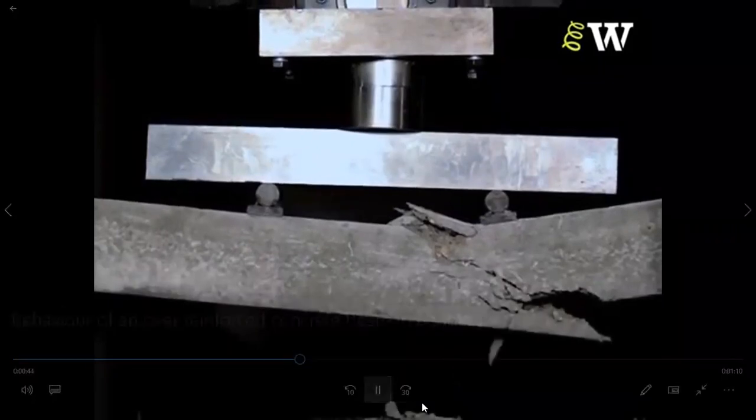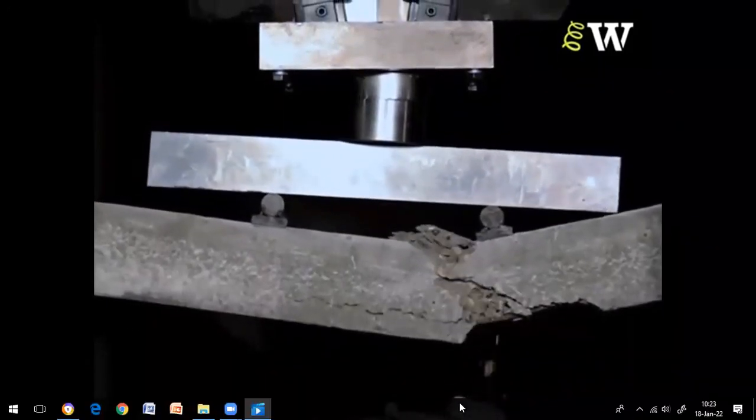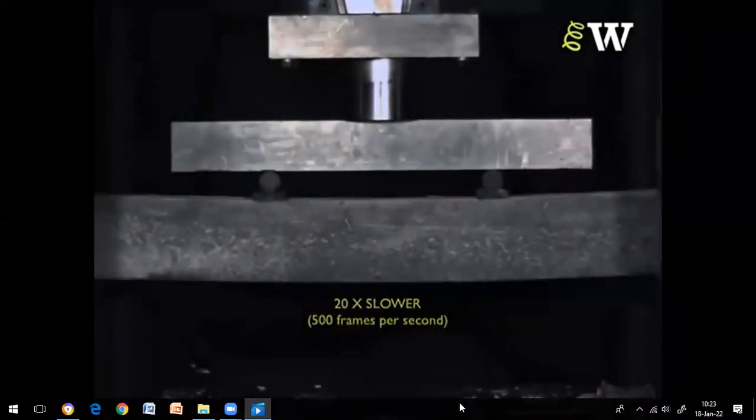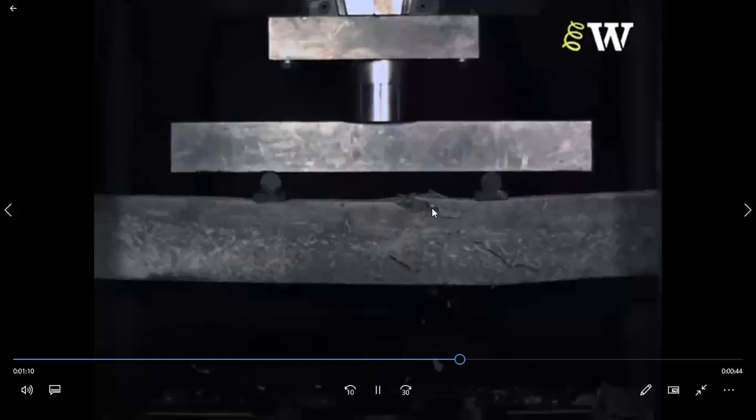That is the reason why we always prefer the under-reinforced beam, because concrete is a brittle material and will fail first, as it undergoes compression failure. Understand? Those who don't know, write it down. Because you didn't do these practical experiments in your BTech, if you at least see these, you can remember. In the slow motion you can easily see how the concrete is failing first.